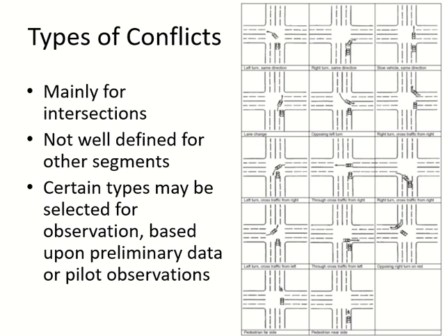It will not always be a conflict, but this is the point where a conflict can happen. So this is a pedestrian crossing, for example, and a vehicle can come at the same time when the pedestrian is trying to cross. But there is a signal. Yes, I'm saying it's a conflict point. It may have zero conflicts because of the signal, right? Clear or not? So where there is no signal, they are just showing the types of conflicts. So the type is general, right? Then you will remove some of them by putting a signal.